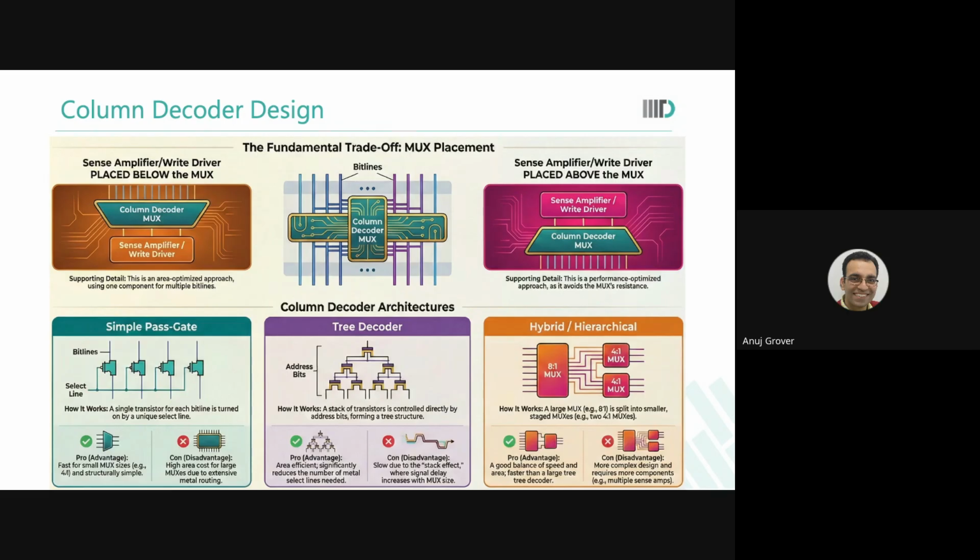Yes. The short circuit condition exists because you did a selective pre-charge off on the other bit line, the other port. So you were not doing anything on my particular column, so the bit line pre-charge was on. That creates a short circuit path from that bit line pre-charge through my pass gates into the write driver of the port.